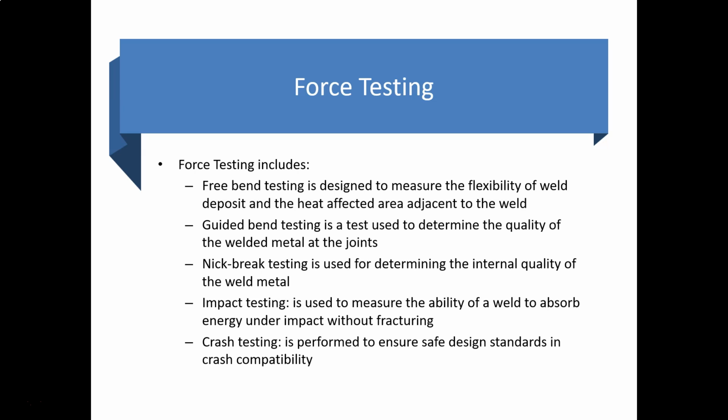The nick break testing is used to determine the internal quality of the welded material. It will detect whether internal defects exist, such as slag inclusion, gas pockets, lack of fusion, and oxidized or burned metal.